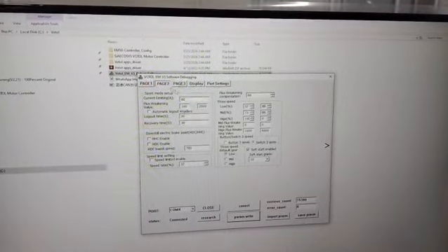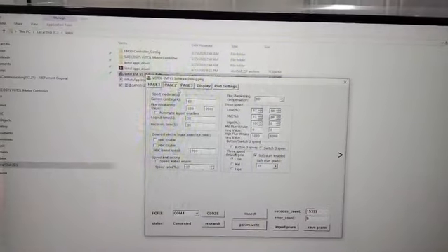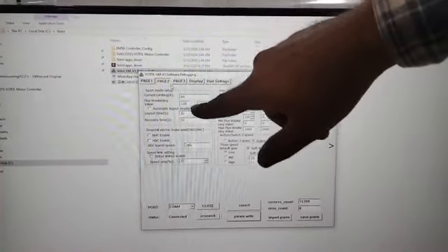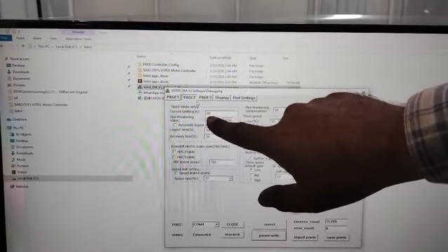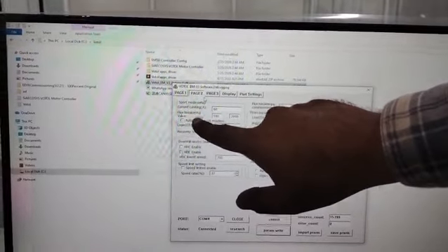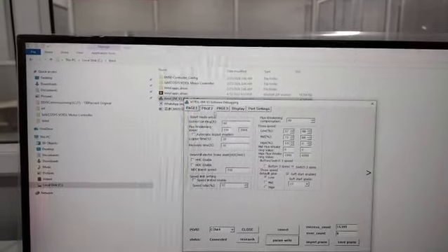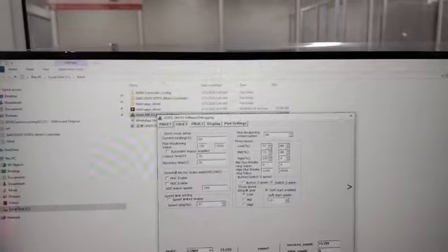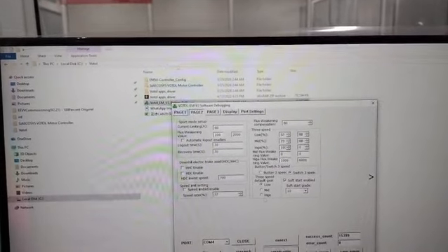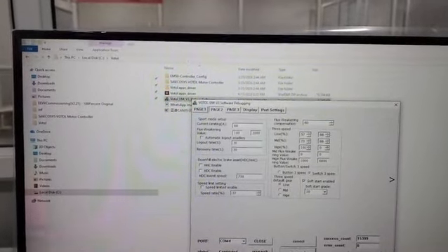On page 2 there are some internal parameters of this motor. We have to arrange a current limit. Here is the field weakening factor. Here is a recovery time, and there are other factors we have to configure in this software. Also we have to configure a speed mode like low, mid or high gear speed mode. We have to set this in this software.